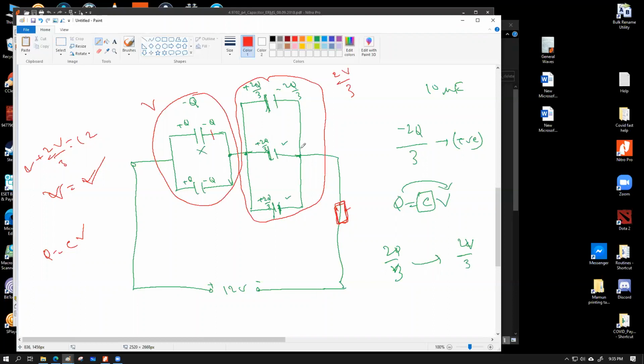The entire capacitor's potential will not decrease. Why will it not decrease, let me explain with reasoning. Try to understand, when the capacitor charges, what happens? Current slowly dies down, right? So when the current dies down, what happens to the voltage difference that is made by this resistor? That also dies down. That is given by I into R.